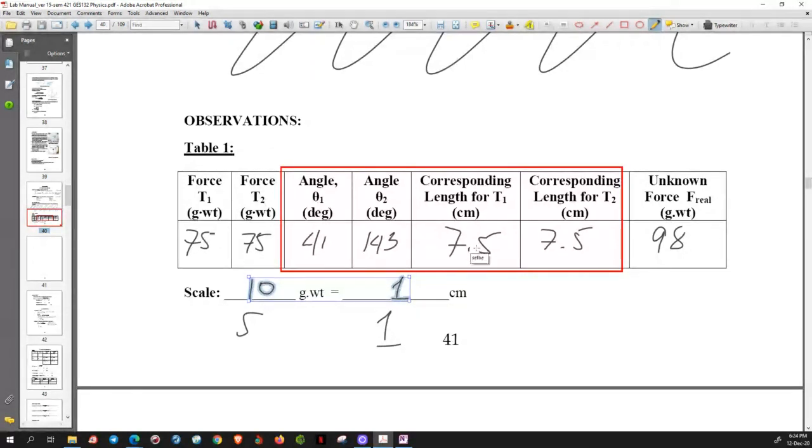It's not a good scale, because here you take 75 divided by 5, what do you get? So you have to think. So it's 15 centi. Next, in the graph paper, do you think 15 centi will fit? 15 centi to the right, 15 centi to the left. So the best scale is always 10:1 for our equipment and our paper.